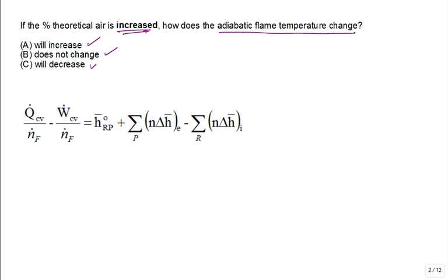What we're going to do is we're going to have the energy balance equation. This term is 0, this term is 0, all the reactants are 0. And we talked about how excess air, will excess air change the standard enthalpy of combustion? No. So this is unchanged. It doesn't matter, it doesn't affect it because look at the formula again. We answered those questions. It doesn't change that part of the equation. But here is where you have the adiabatic flame temperature. It's h bar of the adiabatic flame temperature minus h bar of 298. That's delta H, and that's for each of the products.